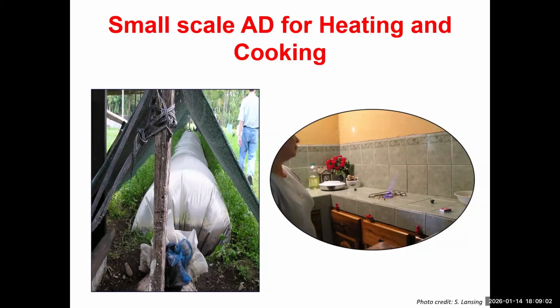But I do want to point out that since biogas has a lower energy density in comparison to natural gas, which is made up of primarily methane, you may notice that the orifice where the gas comes out of the stove is larger.